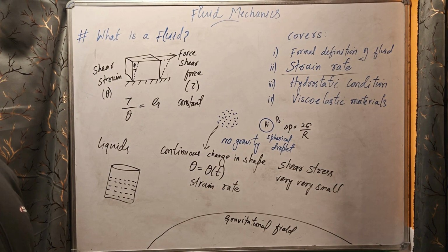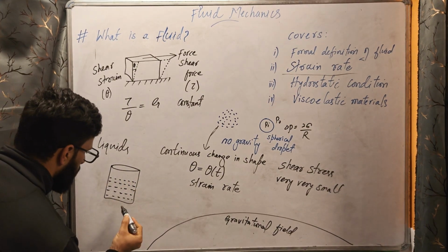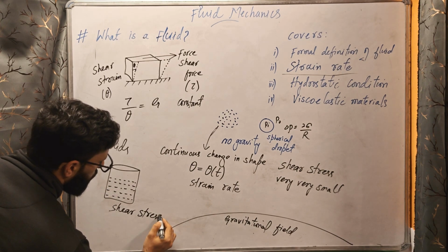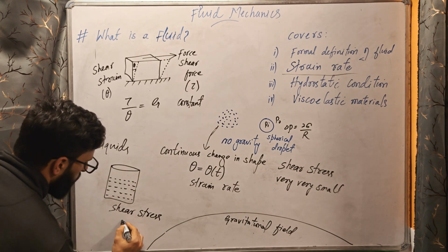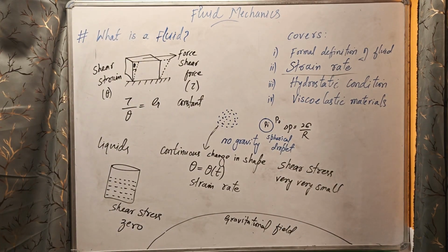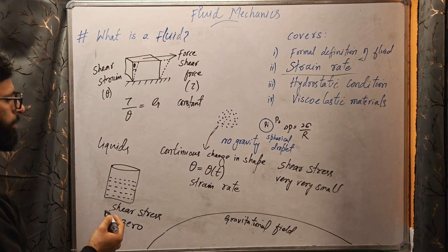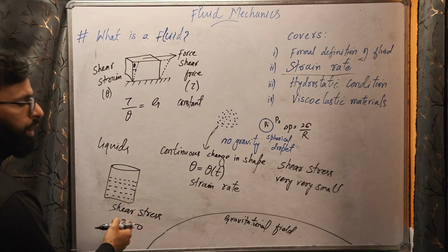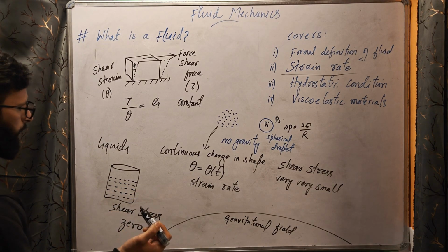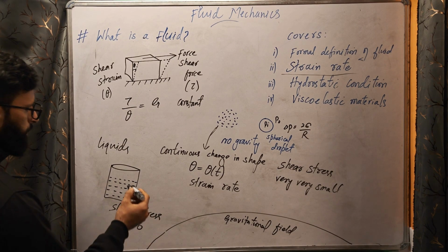We have static liquid. And this condition, when there is no shear stress, where we made shear stress vanish, or we made shear stress zero, is called hydrostatic condition. Now, we do not need to cover this top surface as well. We can keep it open and still have shear stress zero, or liquid at rest.